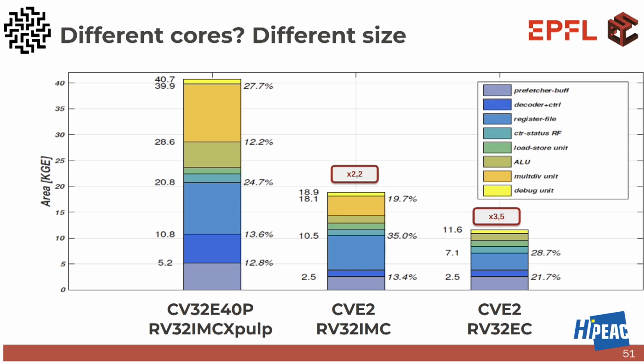But here there is no floating point unit, disclaimer. Because otherwise it's not just 2 times. But it's only 2 times bigger, and why? You see from here, the register file is big. Why is it bigger here? More read and write ports. But look at the adder, or the multiplier, or the ALU, much bigger. And if I even remove the multiplications on the side there, and I only reduce to 16 registers, you see how the register file is smaller, and there is no multiplier and divisor unit, 3.5 times smaller. Good.